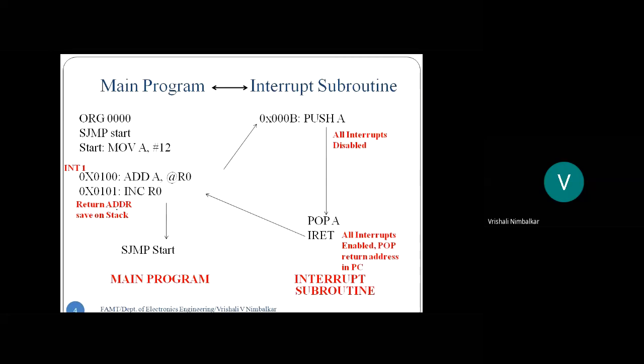Are you getting me? See, can you find this? The same operation we had seen earlier also. Yes or no? The interaction between the main program and the subroutine. When did we see this, students? When we studied call instructions. Call instruction, what does it do? It stops the current execution, jumps to the subroutine, executes the subroutine and returns back to the main program. So this interaction we had seen before while studying the call instruction.